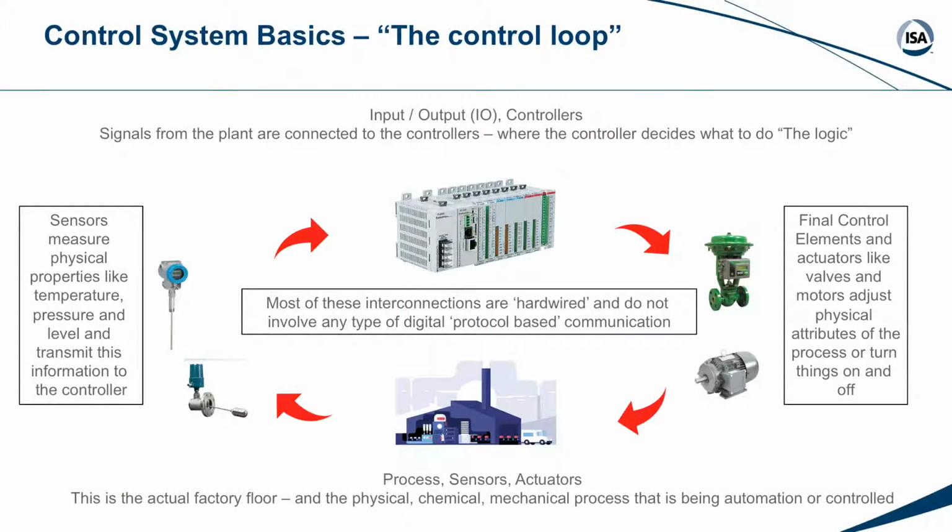So you have a suite of sensors on one side that are wired up to inputs into the control system. The control system is measuring voltage, current, frequency, all kinds of different electrical properties depending upon the sensor, performing some calculations in the middle, and then sending electrical signals out to what we would call final control elements, control valves, variable speed motors and pumps, damper positions, right?